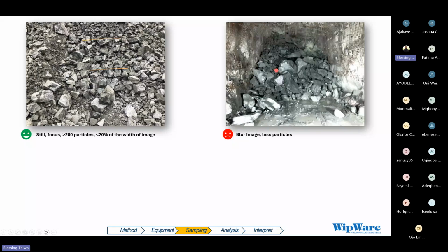You can see we have dual scaling object on it, and it's recommended that you use dual scaling objects when you have the pit floor sloping. For example, if you are closer to an object, it becomes bigger. If you move far away from the object, it becomes smaller. So the software is also incorporating that effect to ensure that error is not setting in because of those materials that are further. With the dual scaling object, it will help you to account for that. And that is what the auto scaling tool will do.